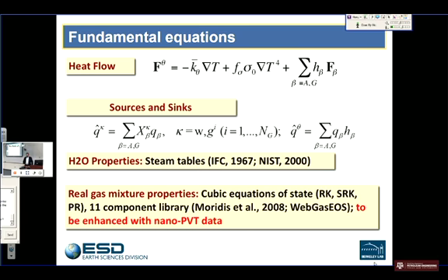And so the PVT of the hydrocarbon phase is always gas, or can it have condensate? It can have condensate, yes. See, what's happening is Peng-Robinson and Soave-Redlich-Kwong allow you to go seamlessly from liquid to gas. That's not the problem. The older one, the Redlich-Kwong, does not allow this.